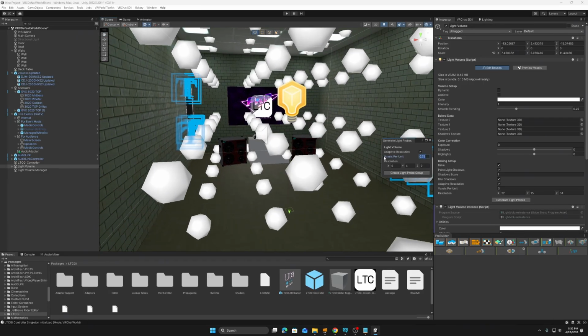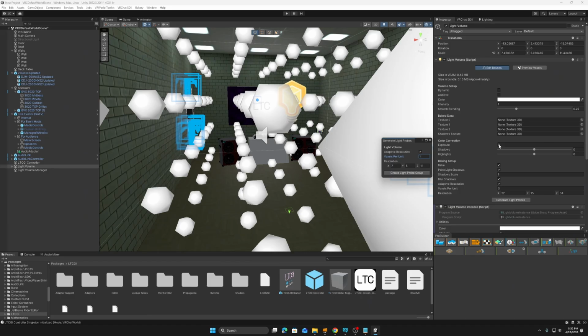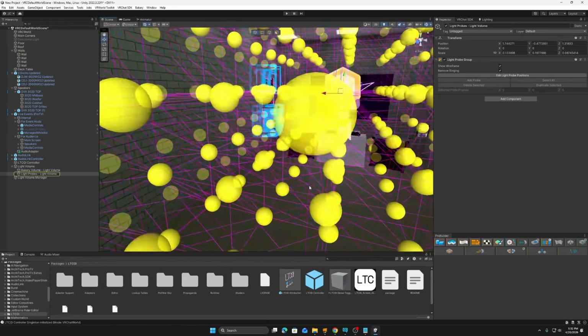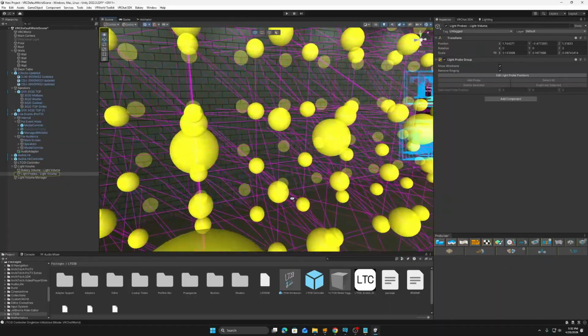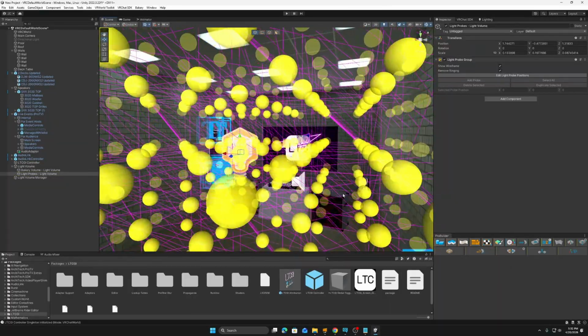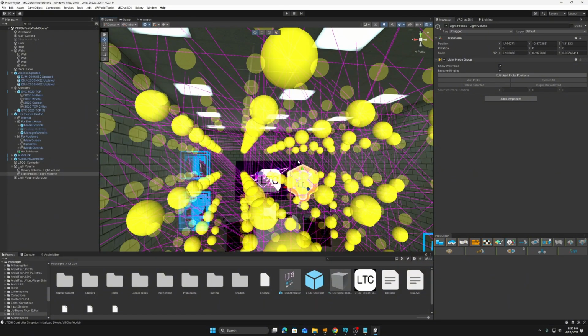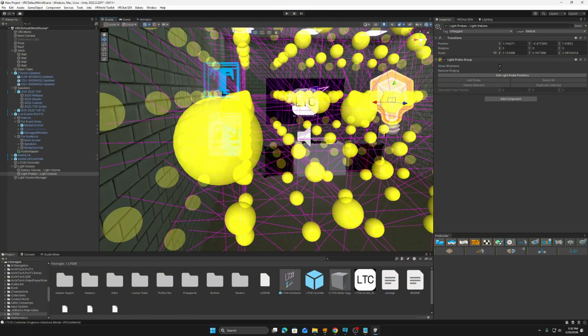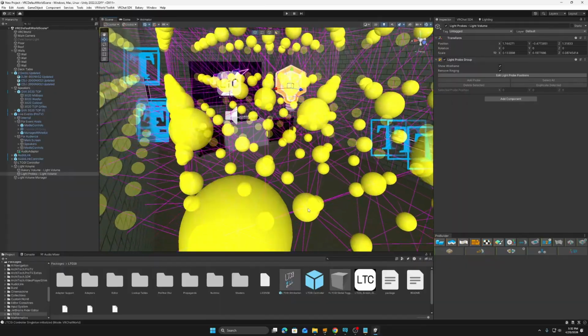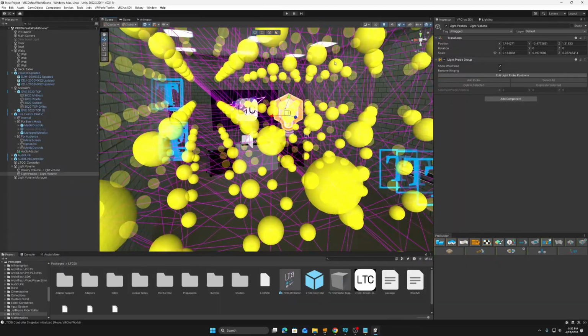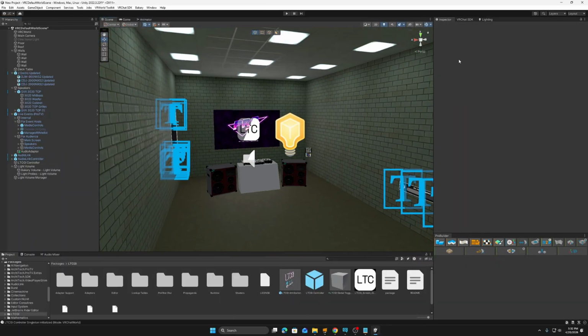I like to go one per unit. And then once you have that set up, this little window should be there that we just did one per unit, and create light probe group. Now that also looks scary, but basically these lights will hit these probes, and then anything off the screen will hit these probes and emit properly on avatars as well as the world. All we have to do is click out of it and it'll go away.